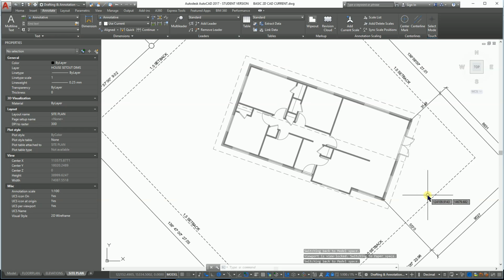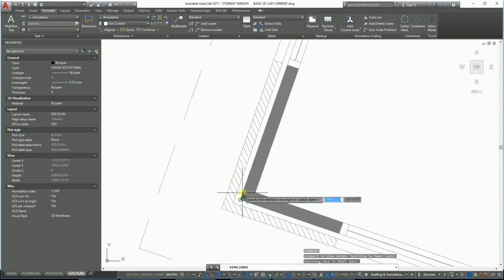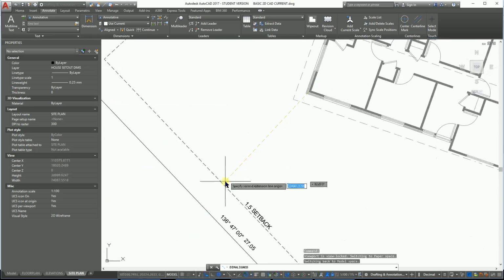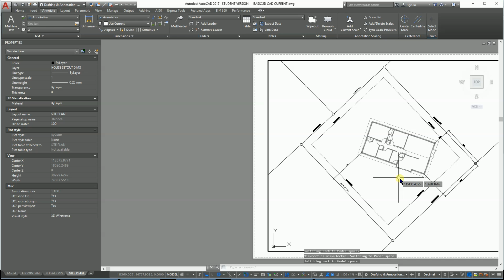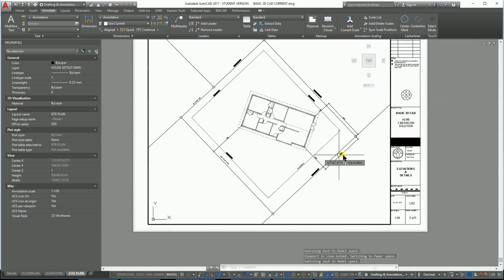I would give another dimension here, and that's this one over here, just by way of a check, so that, you know, the builder, when they set it out, they could check it against this other boundary here. So we're going to just do one more aligned one here, and remember I'm going from the framing line, and just from there straight out and parallel to this boundary to the little right angle one there, and that'll give there 7736. So we've pulled the house over there.